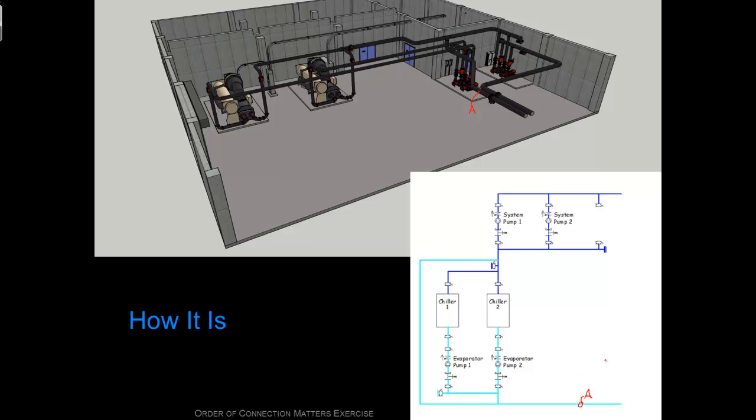is point A. And then I'd literally take my little laser pointer if it's up in the air, or my flashlight, or if it's down low, my hand, and just follow the pipe. And you'll remember from some of the previous posts on system diagrams, in the context of a system diagram, the elbows are meaningless, so I really wouldn't document those 45s. I would just keep following the pipe until I came to a T. And here's a T right here, so we'll call that point B.